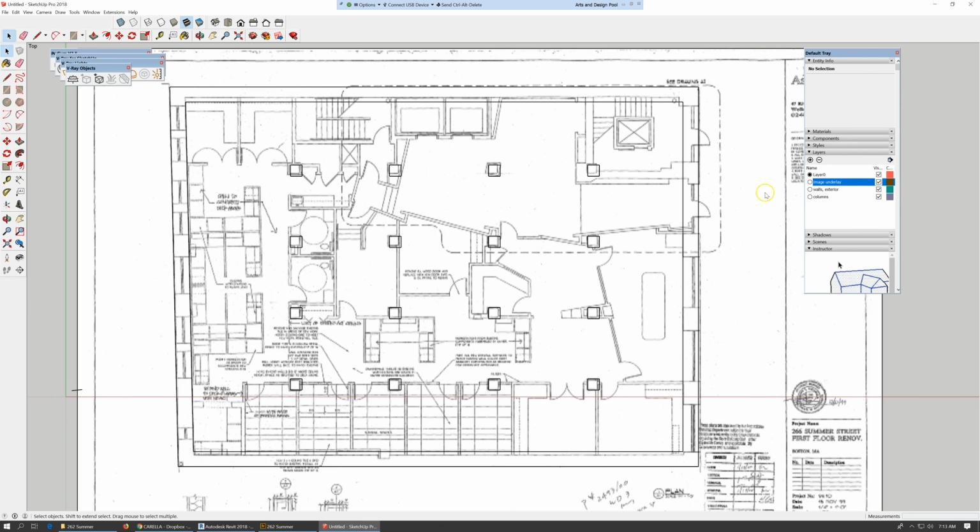We have to identify, there's clearly a stairwell, an exit here. There's an exit here, and there must be some horizontal exit. Either it discharges to a public way on this side, but it doesn't on this side because this is an adjacent building. So somewhere in the building, this exit must be the second way out, and we'll deal with it afterwards. But for now, let's create a layer for the stairs.